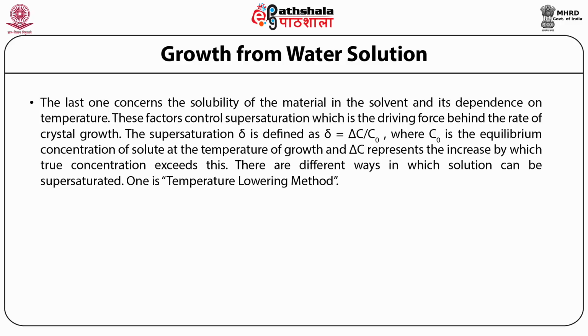These factors control supersaturation, which is the driving force behind the rate of crystal growth. The supersaturation delta is defined as delta equal to delta C upon C0, where C0 is the equilibrium concentration of solute at the temperature of growth and delta C represents the increase by which true concentration exceeds this.